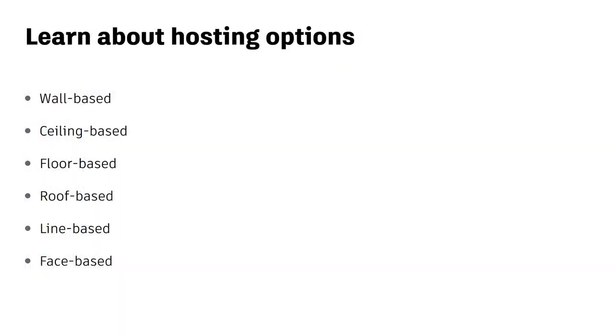When working with Revit families, a number of different hosting options are available. Typically, when starting a generic model, you have the option to choose from a variety of different hosting options. You can then set the category of your family and proceed to build the family geometry.